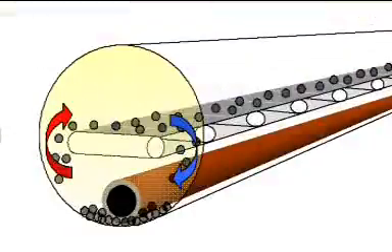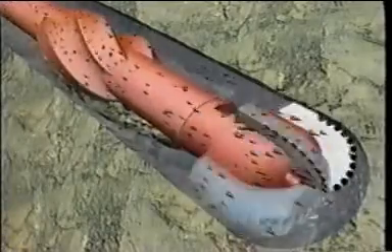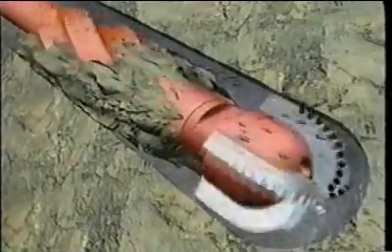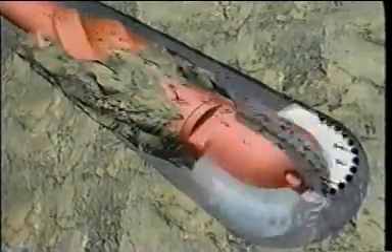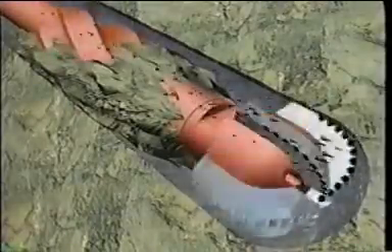The hole cleaning environment in a high-angle well can be viewed like this conveyor belt. If the rotary speed and fluid rheology are not appropriate to get the cuttings onto the belt, then hole cleaning efficiency is going to suffer. Likewise, fluid flow rate represents the speed of the belt, and thus the rate at which cuttings are being removed from the hole.